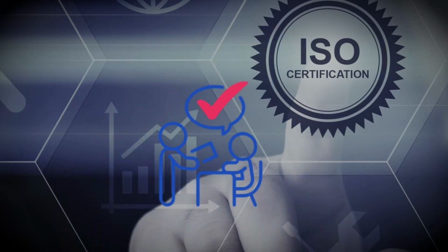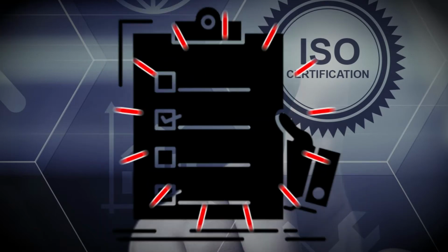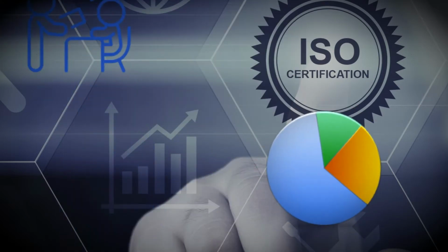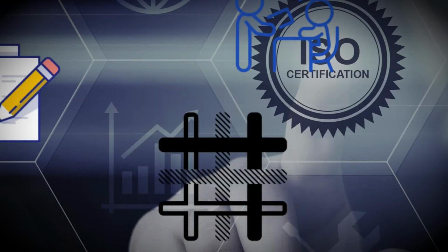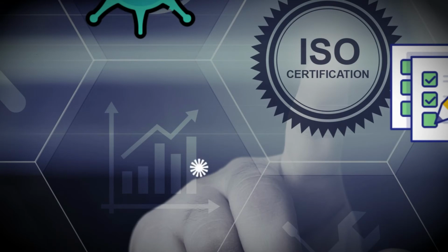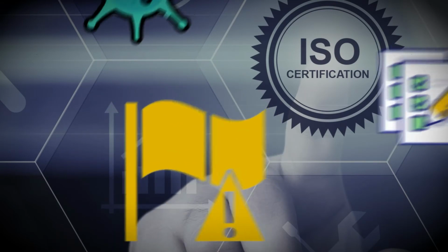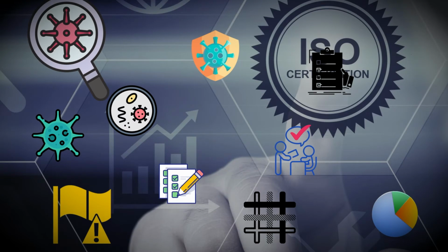Quality departments can disposition issues as scrap, rework, or as is through either a deviation or a waiver. Long-term, quality needs to investigate the problem to find the root cause and suggest preventative action so that the quality event does not happen again. Audit of the preventative action can be scheduled to assess their effectiveness.